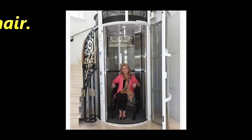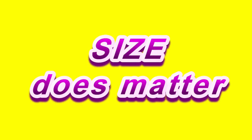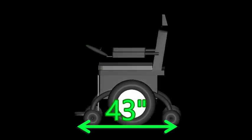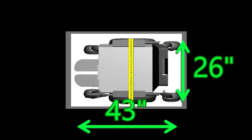First of all, and very important, make sure that you specify and verify that the elevator you are selecting will be the proper size and load capacity that will include a full-size power chair and, of course, you sitting on it. If your power chair weighs 425 pounds like mine does, add your body weight to that for the needed lift capacity. Measure your power chair or look one up in the spec sheets and determine the overall length and width of the power chair, including the foot plates, then add a few inches for additional maneuverability.